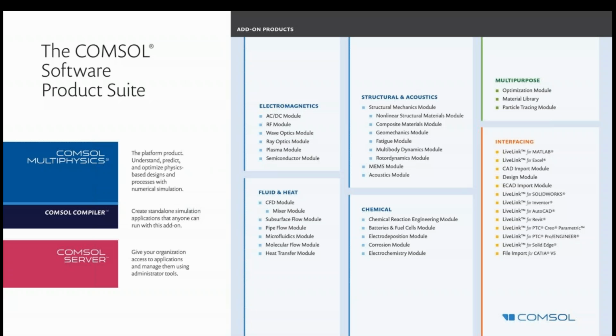So we have the core module, which is called COMSOL Multiphysics. This contains core technologies such as geometry tools, meshing tools, solvers, and also provides a limited amount of modeling capability in the different application areas. There are also a number of modules developed for specific applications that are intended to extend the capability of the software. These are categorized here in 4 key sections: electromagnetics, fluid and heat, structural and acoustics, and chemical. We also have some multi-purpose modules, which are for doing things like mathematical optimization. And there are interfacing modules that allow you to connect COMSOL either to CAD or to something like a scripting environment such as MATLAB.